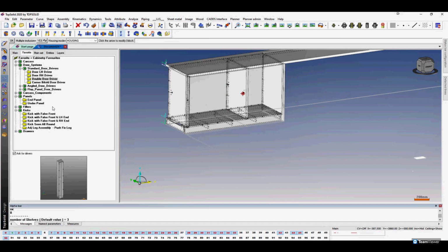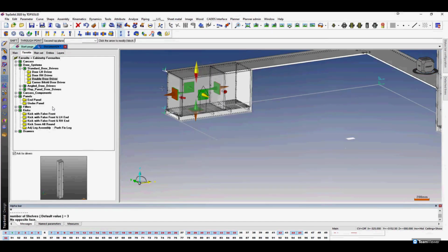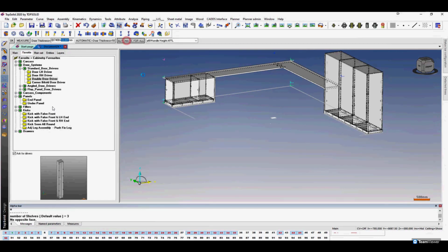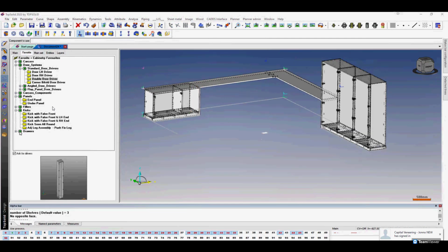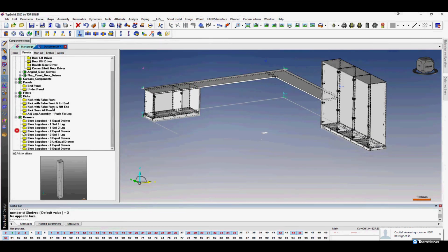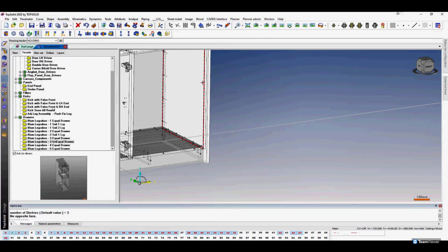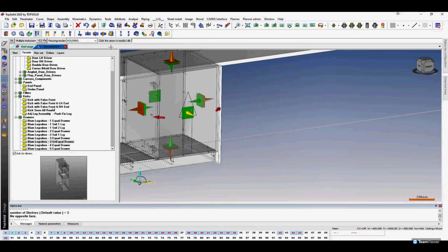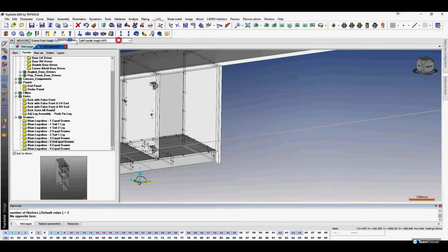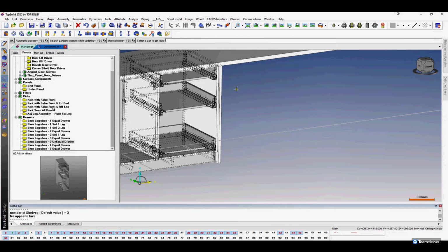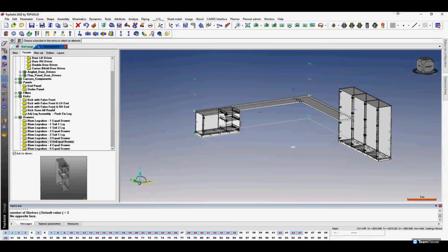Now I'm bringing in double door drivers. So double doors, nothing special there. We're just bringing them in to finish off the inclusion. Now drawers. So bringing in 3 unequal drawers. The unequal drawers, we'll do automatic for all, and then change the top drawer front to be 125, the second one to be 250, and then the third one will be whatever's left over.